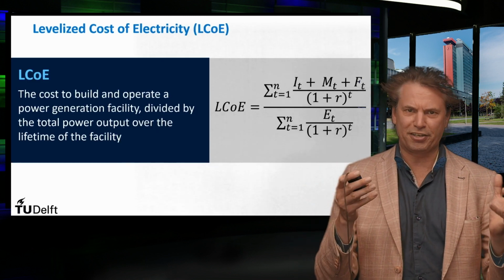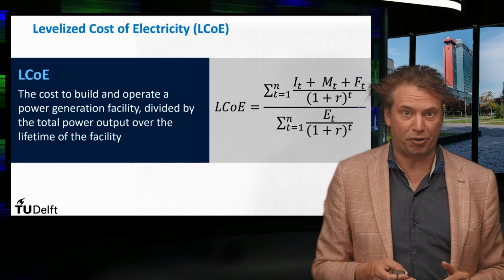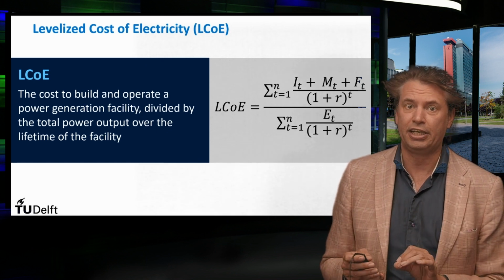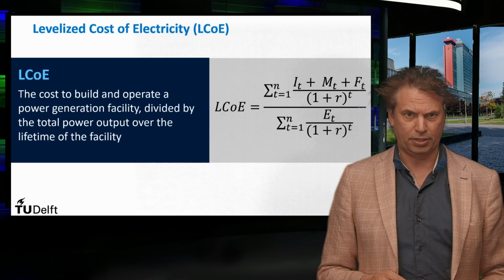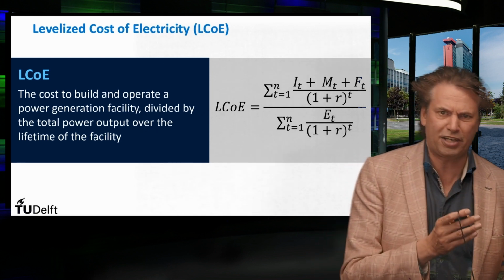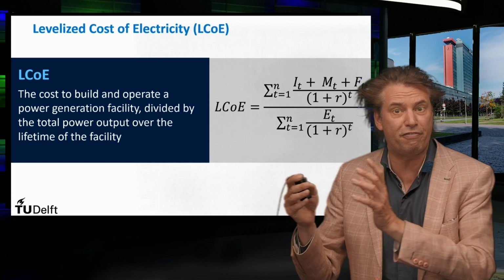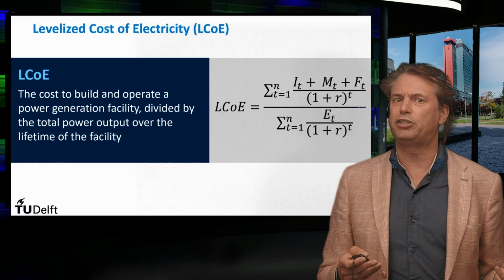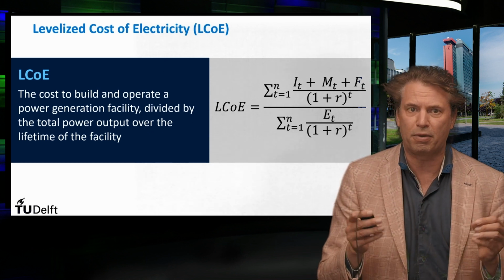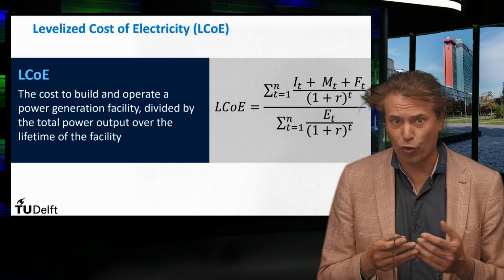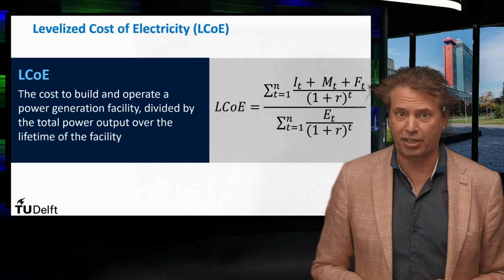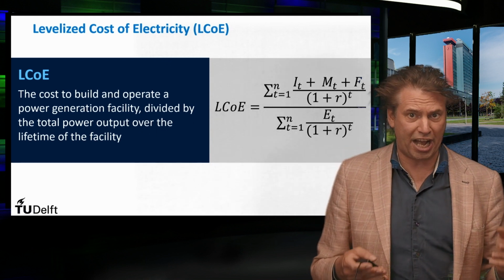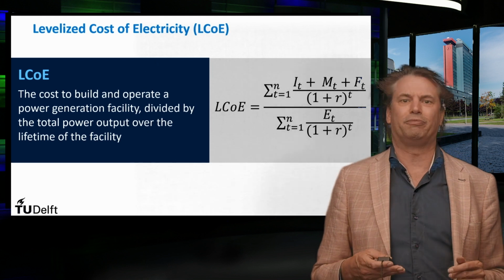Let us start by defining the levelized cost of electricity, or LCOE. The LCOE is defined as the cost per kilowatt hour of electricity generated by a certain energy system. It is generally used to compare the lifetime cost of projects based on the various power sources. For the levelized costs, the overall cost of an energy plant during its useful lifetime are calculated. Then the overall energy production of the plant over its lifetime is determined. Using these two numbers, we can then figure out the LCOE of a given energy system.